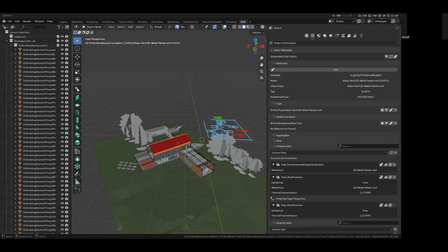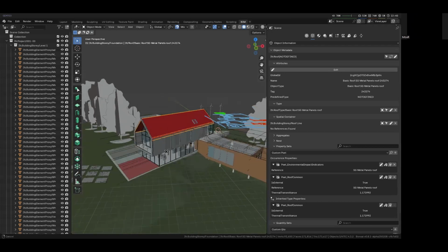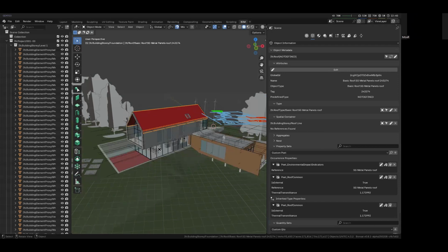Okay, it's a roof. What type of roof is it? Oh, it's a hipped roof. Okay, what type of hipped roof is it? Oh, it's a such and such and such. So IFC is fairly shallow compared to these other more famous classification systems because it's only 2 levels deep. And I think that's really quite nice, its shallowness, because very often you will want a starting point. You can think of IFC as a foundation or a starting point to describe your information. And then if your project does need something more specific, you can then connect it to have another more detailed classification system in addition to your existing classification code, the existing IFC built-in classification system. So 2 levels deep is really quite nice.